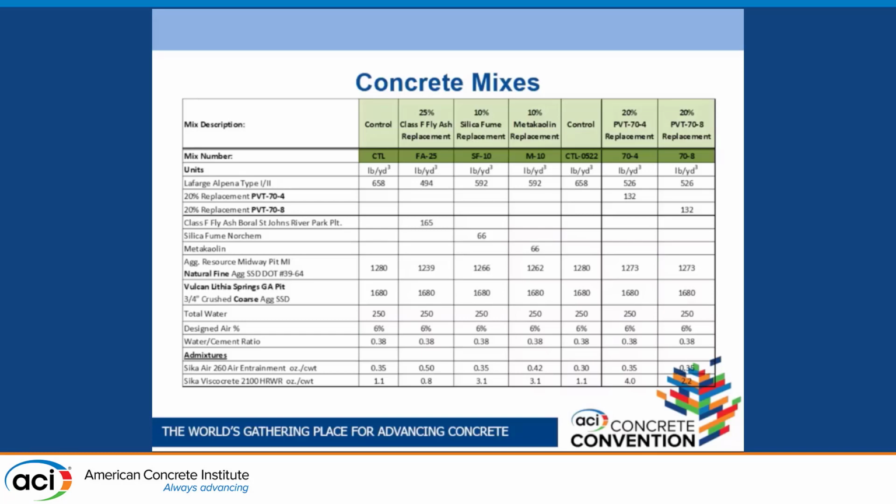You see the water content is also very low, and these are basic designs. And I think the bottom thing is the admixtures we had to use. In order to get the same amount of slump, it was basically less, right along the line with other materials. So basically good performance on that end.